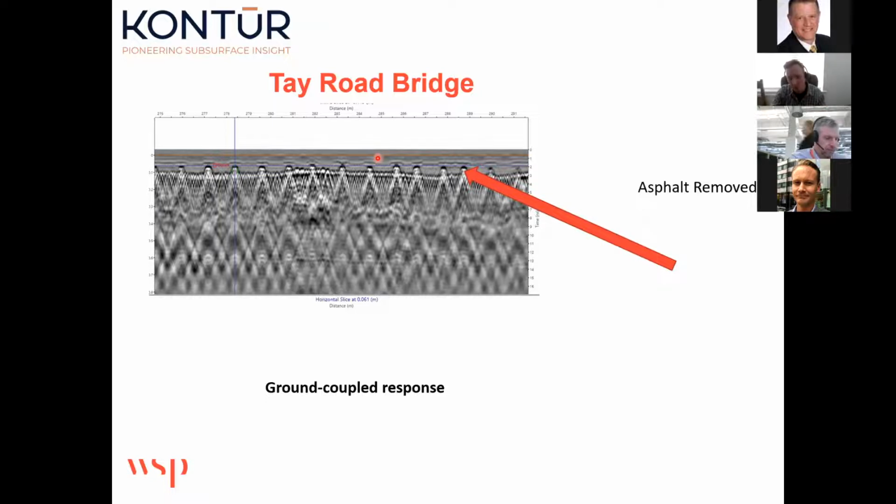The time window also affects the size of the steps, in our system anyway. If you have a larger time window, your incremental step between each frequency, let's say from 100 to 3000, will be smaller. If you make the time window shorter, then your jumps will be more like 20 megahertz steps instead of something like 4 megahertz steps. Okay, so you get a richer response if you have a bigger time window.